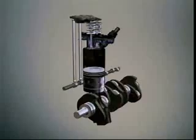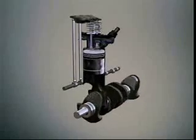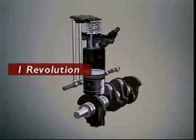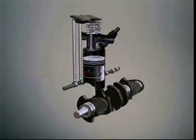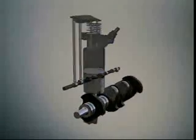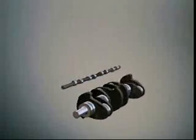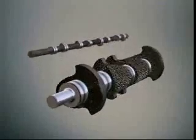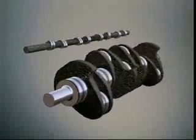They open and close once. So the cams must make just 1 revolution, and if the cams make 1 revolution, so must the camshaft. But in each 4-stroke cycle, the crankshaft rotates completely twice, so the camshaft must rotate at half the speed of the crankshaft. This can be achieved by gears.